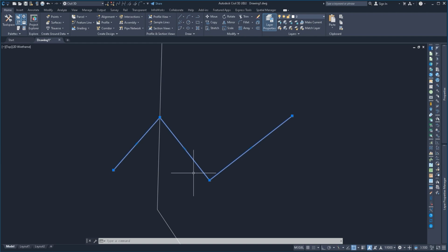This is because these patterns are much easier to implement and to work with than curved patterns. If you're creating curved style patterns, you're also going to inevitably need high-end surveying equipment to be able to implement them on the ground accurately. Whereas if you're planning with angular patterns, you can implement them on the ground using very basic equipment, for example, like a map and a compass. Or you can just use your smartphone or some kind of handheld GPS device.